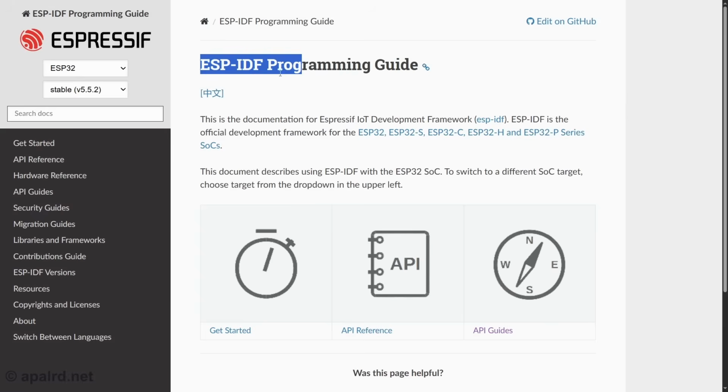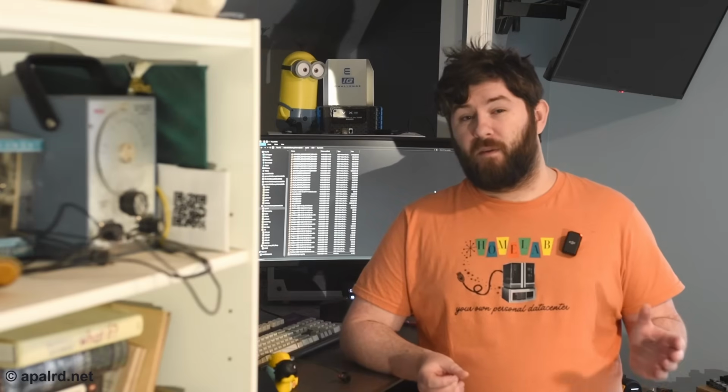The reason I chose to go straight to C coding instead of using an easier approach like ESPHome or MicroPython is mostly because of the IPv6 support in ESP-IDF. With modern ESP32 framework versions, IPv6 is a total first-class citizen, enabled by default, super easy to use. I can't say the same for ESPHome, where it's enabled by default, but it still requires v4 to function, or MicroPython, which doesn't yet have IPv6 support on the ESP32 port. So for me, using IPv6, it was a no-brainer to use ESP-IDF. Also, Espressif's documentation is actually incredibly good, and I found many great examples from their own documentation site.